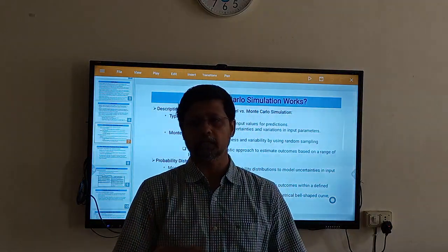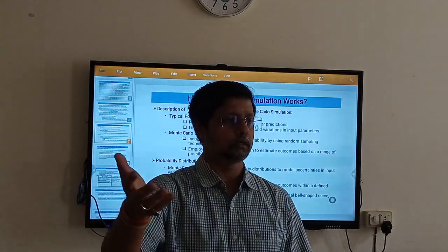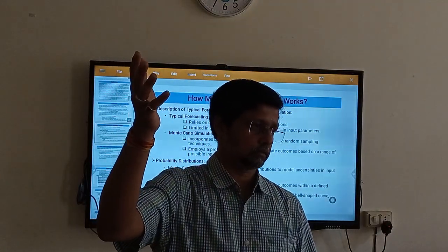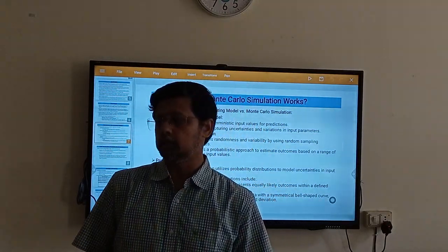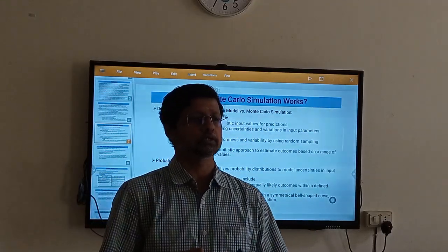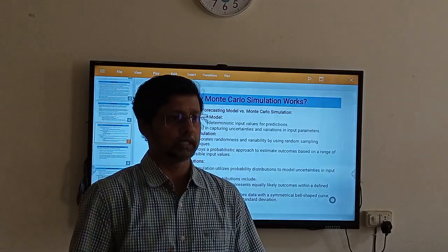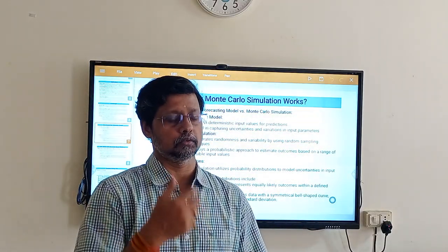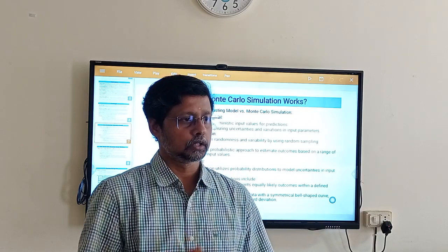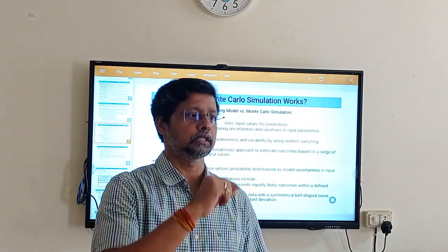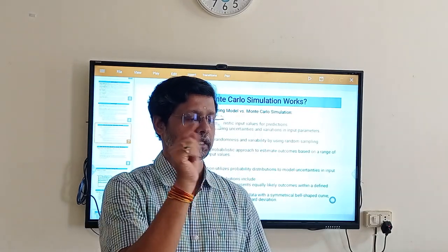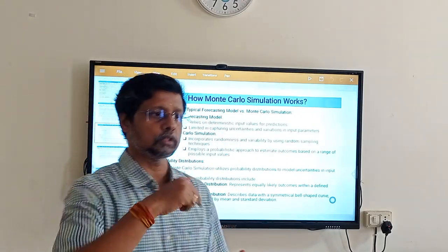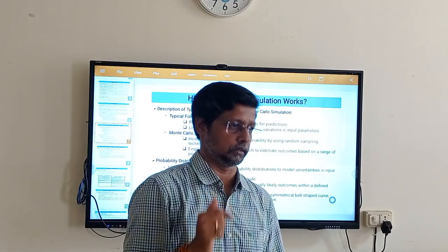And I also take care of what will happen if I enter, accidentally or purposely, the saturation region, right? Even if I want to use a transistor as a switch, I can, because I need to make certain changes while doping. If you want to use the transistor only as a switch, it should not spend more time in the active region. There should be a cutoff region and a saturation region, and you can treat them as on and off. How do we know? Because we know the characteristics. That's why we are able to predict. Understand?